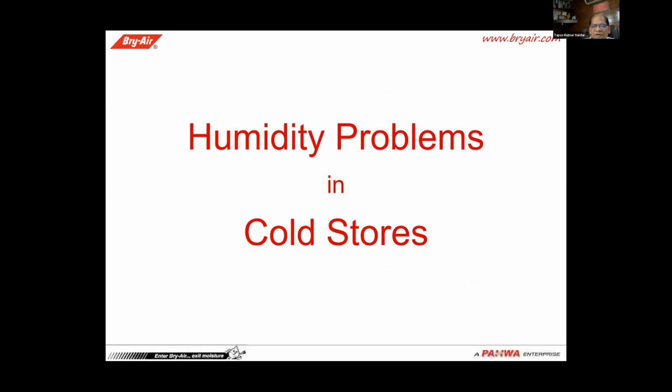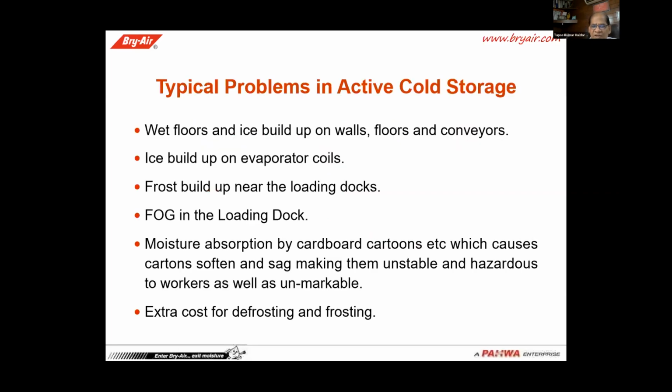Mainly today's topic, which I am going to discuss with all of you, is the humidity problem in cold storage. How does it occur? Generally, the problems we face in cold storage are wet floors and ice buildup on the walls, floors and conveyors. Sometimes a conveyor comes from the cold storage to the other area where loading and unloading is done, but due to icing, we face problems in the conveyor. If there is ice formation on the floor, people can slip and fall down. So there is a problem.